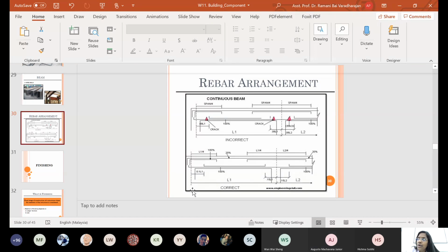Only the sizing, the spacing also you design one after another. What are the main rod spacing, secondary rod spacing, and number of rods, and then what else? Mainly the size, and then beam size. Beam size is also changing, column size is also changing. Well, the sketch will be the same. All will have the same detailing. You should have the size of the beam, reinforcement detailing, mainly the size and the spacing and the cover, and all these things.